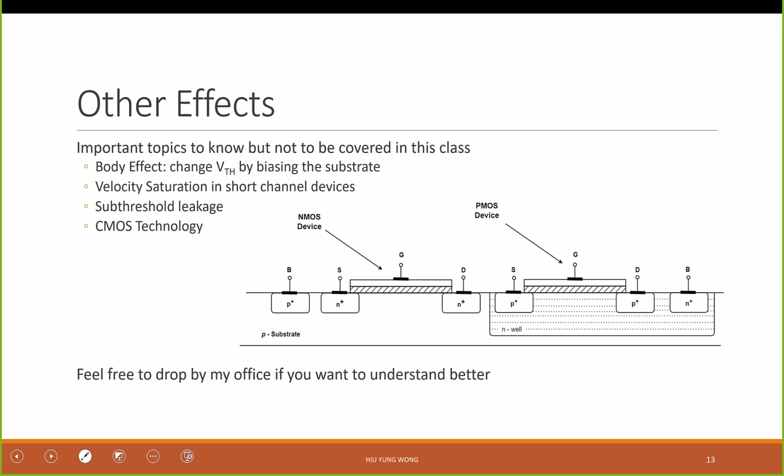And in Intel's chip, how many transistors do you have? 1 billion. So you have 1 nanoampere leaking each. If all of them are off, just sitting there is consuming 10 amperes of current. Okay? And that's why the rocket nozzle or the sun temperature analogy we talked about earlier, right? If they just keep scaling and increasing the frequency, eventually the whole chip will melt. And that's why they became multi-core.